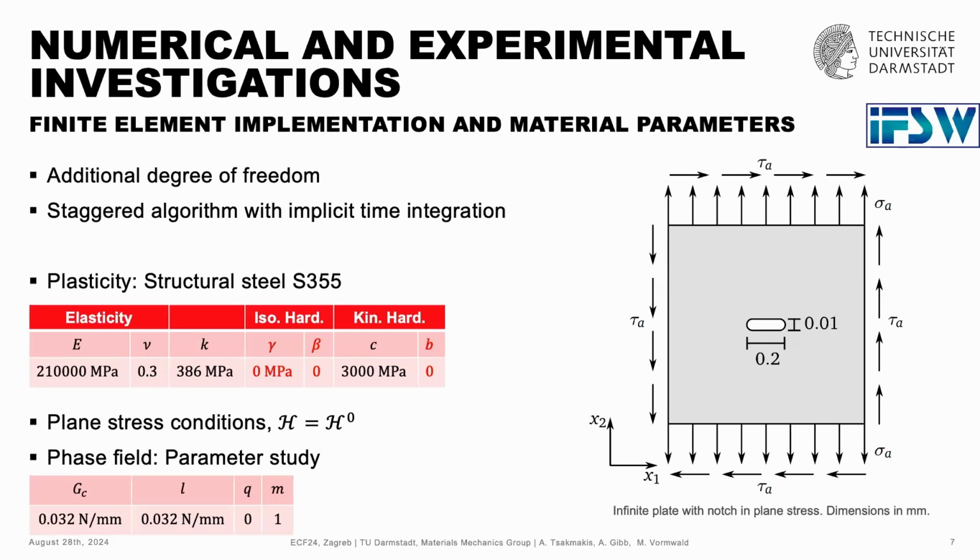A very major issue when it comes to the numerical evaluations is actually the numerical effort one has to deal with. So for these simulations here, we chose to stick with the easiest formulation we came up with. So essentially, we will use only linear hardening here and a very simplified geometrical model. Although, again, if we wanted to include nonlinear hardening, essentially, we get the same results. It's just a quantitative difference. We also make use of plane stress conditions and the set of material parameters for the phase field part.